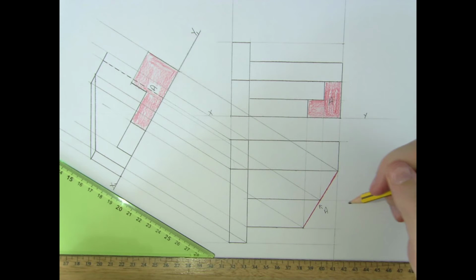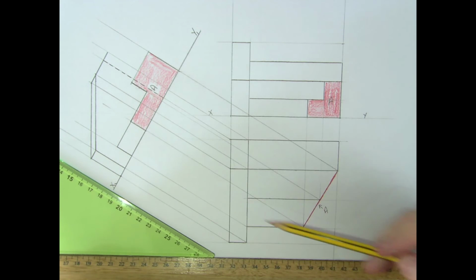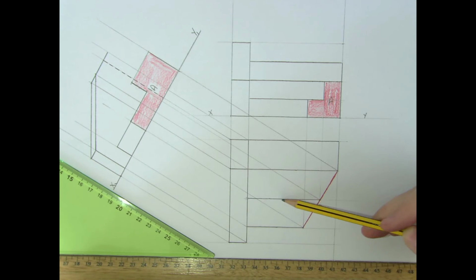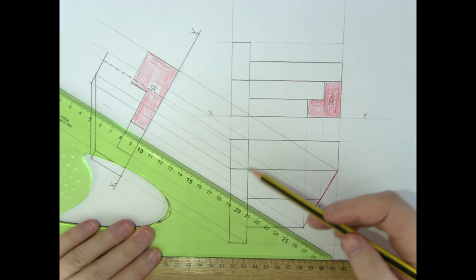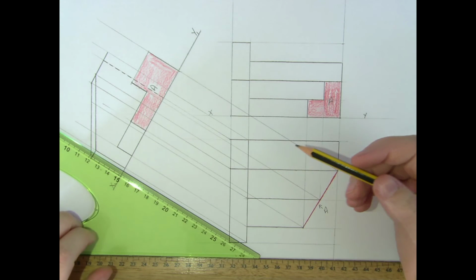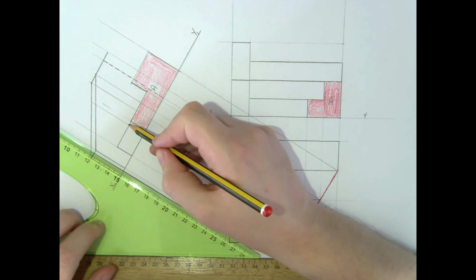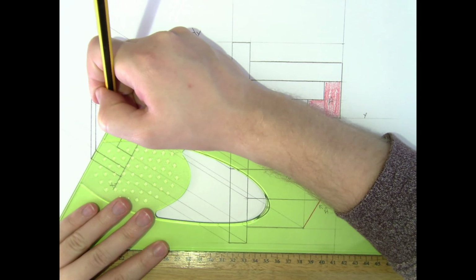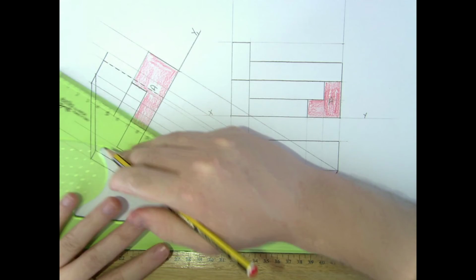Okay, so going back to looking at the steps, we have the surface A part of the steps. Now let's find this corner inside here, where the second step intersects with the wall. So this is going to be projected up along. I'm going to need to locate the heights, so it's going to go back as far as there, it's going to go up the height of 15. So that's going to extend onto this point.